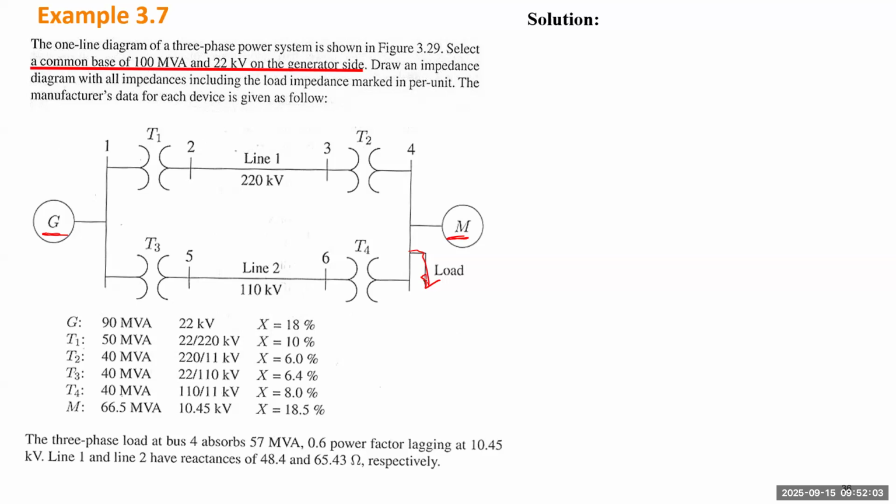There are two transmission paths. One path is at 220 kV, the other at 110 kV. The generator operates at a lower voltage. Those are the summary of the nameplates from all the equipment. The generator operates at 22 kV, so I need this step-up transformer to change from 22 kV to 220 kV and deliver through this transformer.